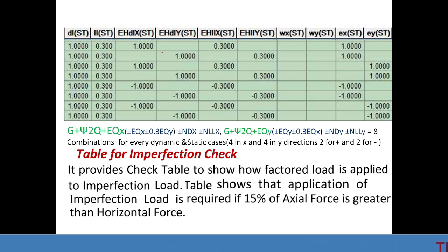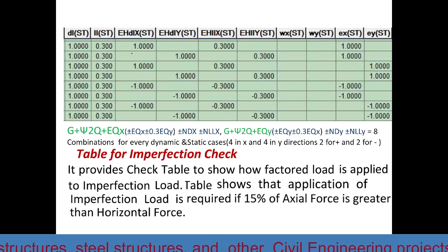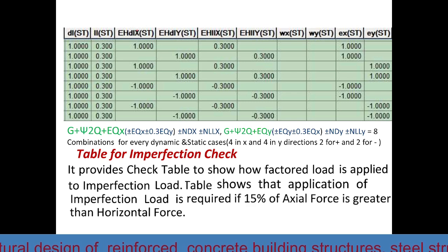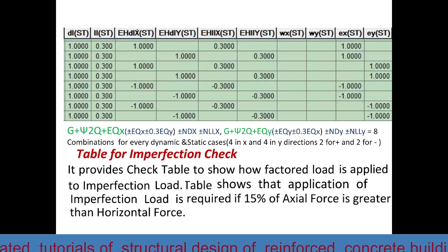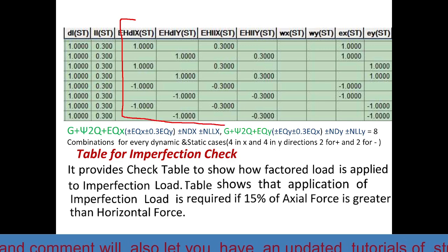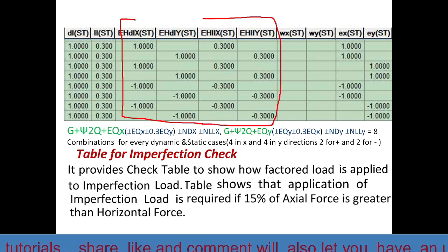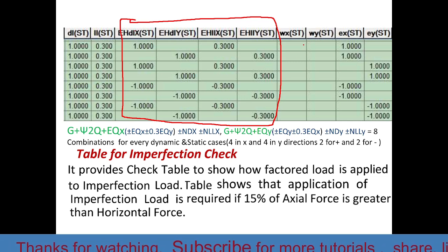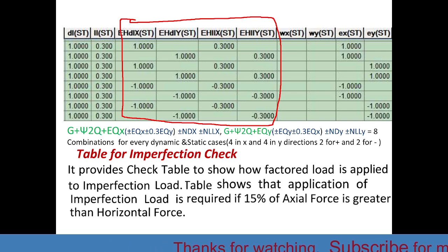Okay, now this is how to combine the notional load with the seismic load. So here in this x direction, this is the notional load, all those are the combination factors for notional load, for the dead load and the live load, and this must also be combined with the seismic load in x and in y direction.